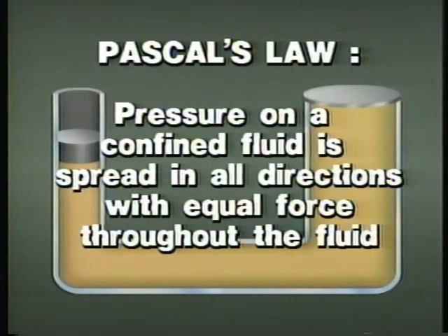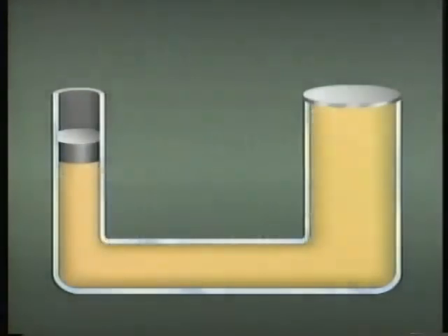One of these principles, called Pascal's law, simply put, states that pressure applied on a confined fluid is transmitted in all directions and acts with equal force throughout the fluid. Let's look at an illustration to see the role that Pascal's law and other principles play in making hydraulic systems work. This illustration includes two containers with hydraulic fluid. The containers are connected by a line that provides a flow path between them. One container is wider than the other. We'll see why a little later.